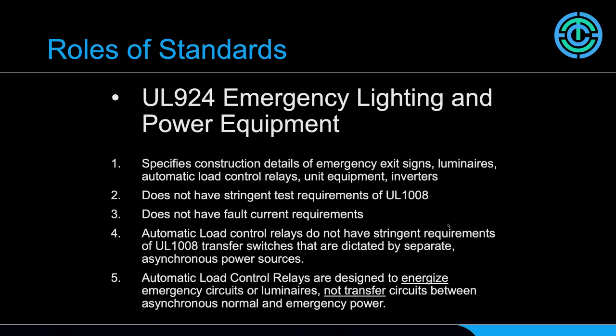It does not have the stringent test requirements of the UL 1008. It is still a very high standard, but again, the UL 1008 is mainly in the power stream, so those devices have a much higher test requirement to meet that standard. UL 924 does not have fault current requirements as well.